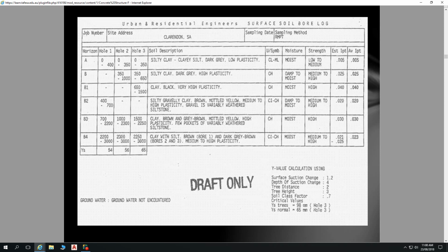I can't remember the classification of Y values off the top of my head. I think they might be in the slides here for stable, moderate, highly, and extremely. Oh, and then after that E, you've got P class soils as well. P class is something different. Once again, that's problematic class soils. That's for individual assessment. So if I had H1D/P, that's a highly reactive.